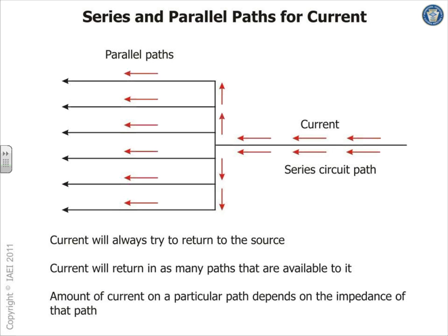So just to emphasize, when we talk about bonding the neutral at the second building, why don't we do that? Who cares? Because your neutral current under normal operating conditions will be going through your pipe system. Do you want this to happen? You don't want this one to happen.